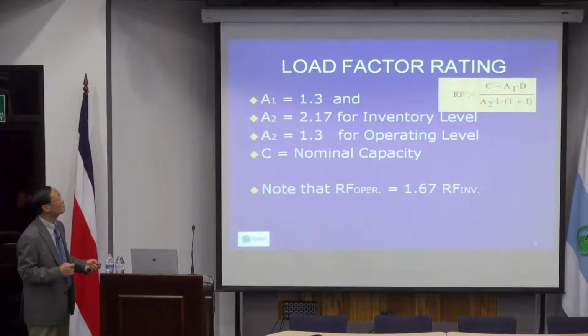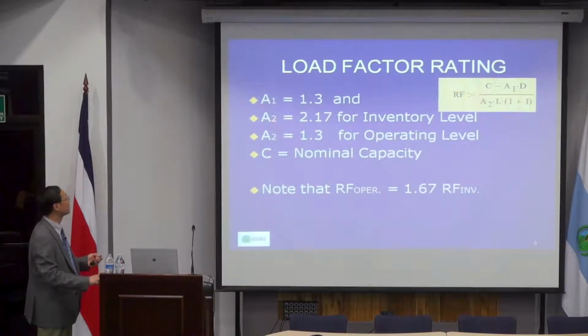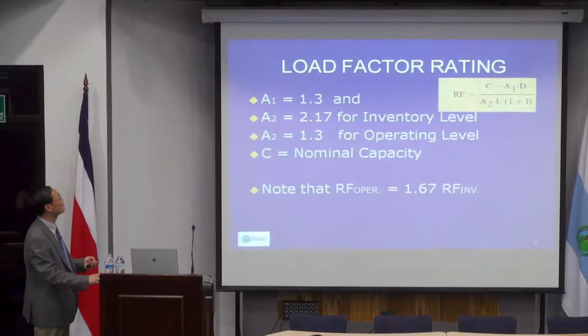Then for the inventory level, we use, like for LFD design, the live load factor of 2.17 and dead load factor of 1.3. So we use the dead load factor and live load factor for inventory, which is the same as design. And we rate for operating level. The dead load factor does not change, it's still 1.3, and we use 1.3 for live load as well.